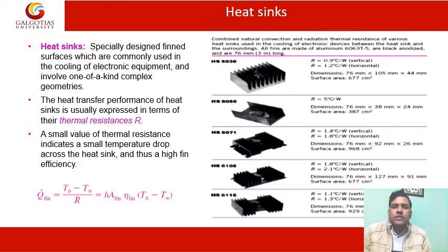So this is the concept of fin efficiency of a heat sink, and the heat transfer is given by this relationship, where Q fin is equal to T_B minus T of the ambient upon the resistance offered by the fin, that is equal to h A_fin into eta of the fin into (T_B minus T infinity).